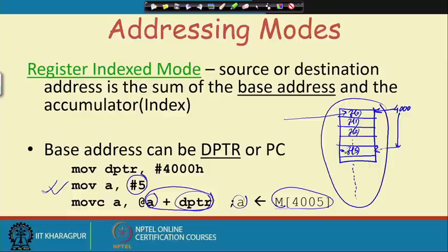This is very useful when you have this type of lookup tables stored as arrays in the external memory, and then you can use them in your code. For that purpose this has been thought about, and since these microcontrollers are used for embedded applications, many times we have this type of situation. Maybe we have some complex function that is difficult to compute every time. So what is done is that the values are computed once only at design time, and kept as a lookup table, and that becomes a part of the code.